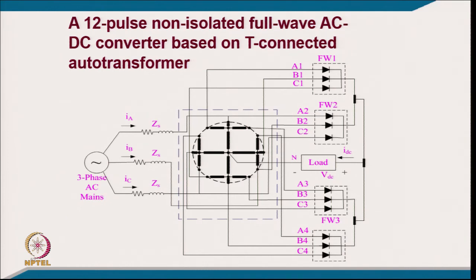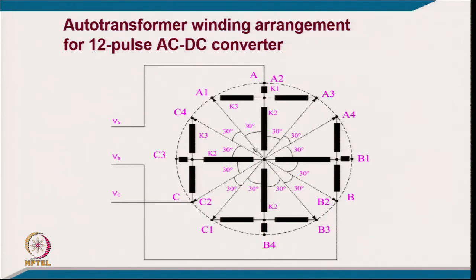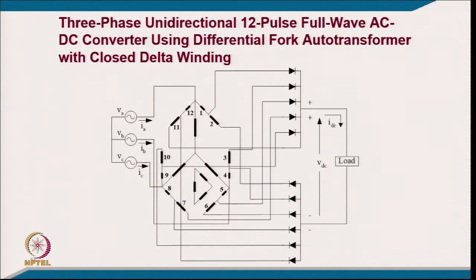Okay, you are converting a 3 phase supply with this T connection into 12 phase, and you are using 12 diodes, and with respect to neutral you will have a 12 phase voltage of equal magnitude, which gives you a 12 phase supply. And similarly, here is the transformer and how you are going to design it with the phase shift, and these are the K1, K2 constants I was talking about in the previous equations. It is a simple geometrical relation, for which even school mathematics is enough for the design, but of course it is a circle, not an ellipse, so you have to be cautious.